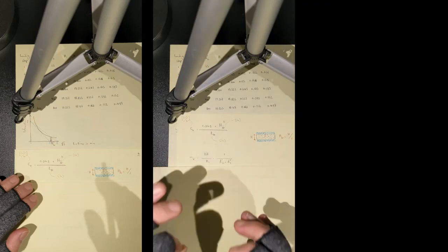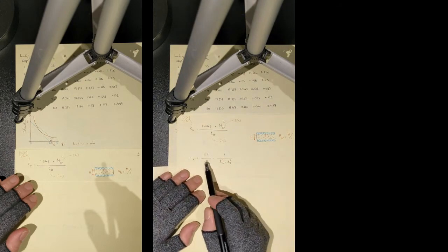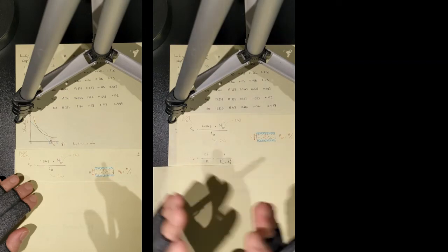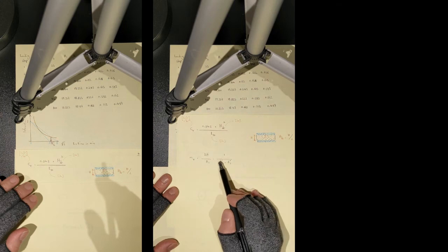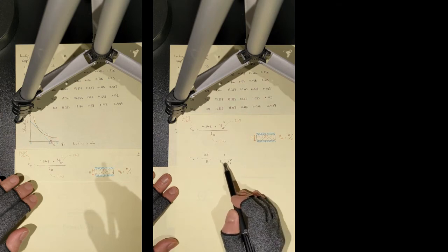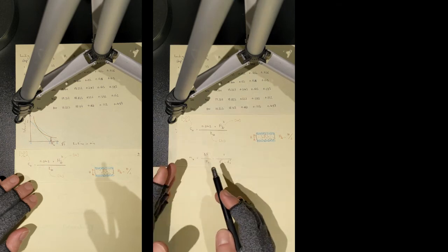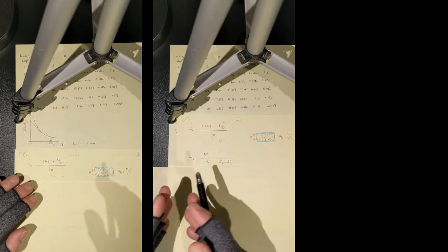the displacement, the dial gauge reading, delta H, divided by H1, the initial height of the test specimen at the beginning of that loading step, whatever that loading step is, multiplied by 1 divided by sigma dash 2, effective stress 2, minus sigma dash 1, effective stress 1. Sigma dash 2 is your topped up stress, and sigma dash 1 is the initial effective stress. So let's say